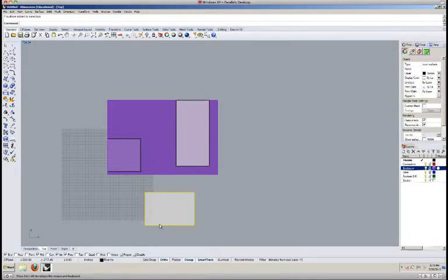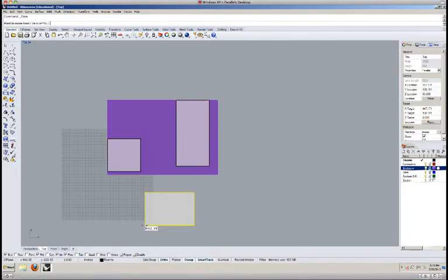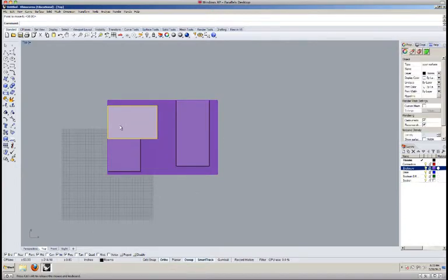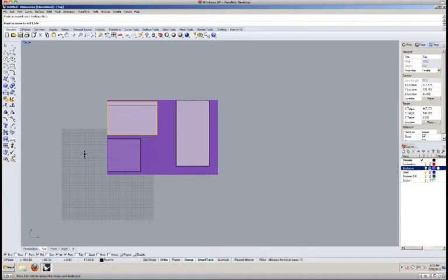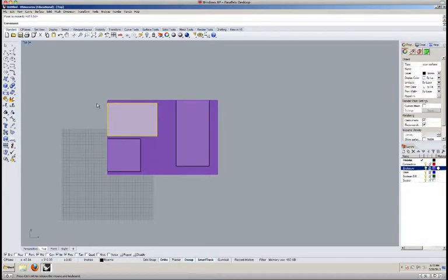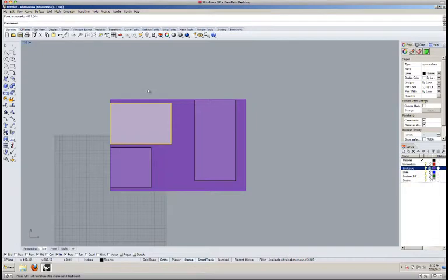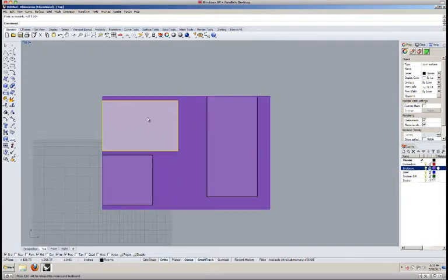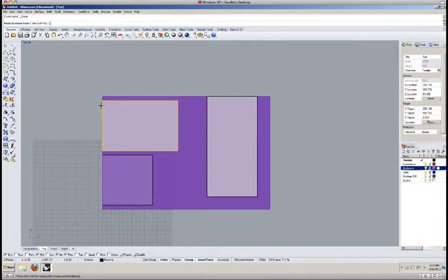And again, this is just me moving the volumes, not really thinking about the design. I'm going to go ahead and place this last one relative to one of the previous volumes, and then I'm going to move it 1 foot away from it, and I should still be 1 foot away from my edge. And maybe this one I want to have the exterior face open to the sky, so I'm going to move it in from the exterior face on this west side, and then I'll be able to open it to the sky eventually. So I'm going to move it in 3 feet.